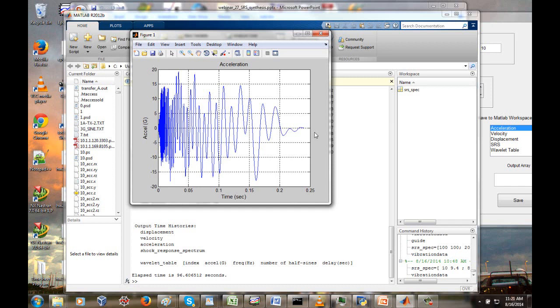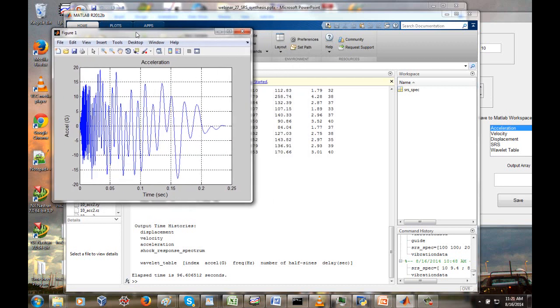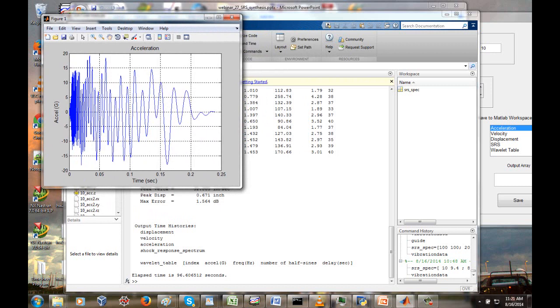But if we are concerned about nonlinearities and multi-degree of freedom behavior and other things, there are other tools we can use, particularly if we need to replicate the recorded field waveform in the test lab. But today we're saying we don't need time history replication. That's a topic for another day. So we're saying as long as we meet the SRS, that we're good to go, even though that's a funny looking shock pulse. Now, the final acceleration is 0.